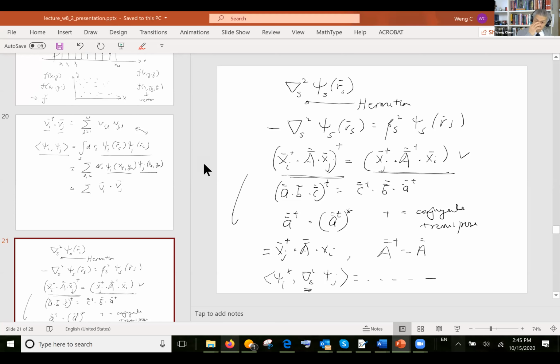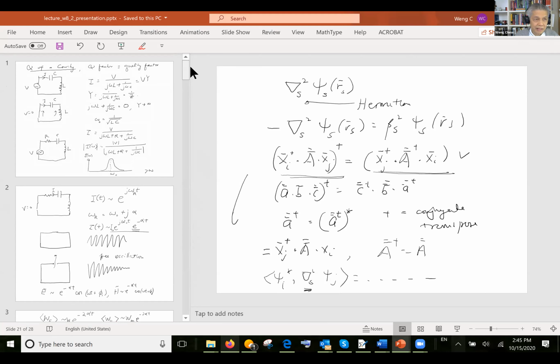Okay, so let's regurgitate what we studied today. We studied the Q of a resonator. We tried to get intuition by looking at the Q of an LC tank circuit. If you have an LC tank circuit, you have resonances, and if there's no loss, then the resonance frequency is purely real. However, if there's any loss in the system, the resonant frequency is never real, and hence the denominator would never go to 0. And if you plot this transfer function, it will look something like this.